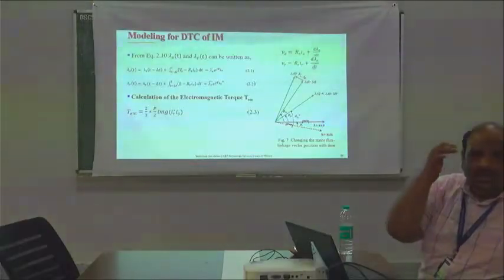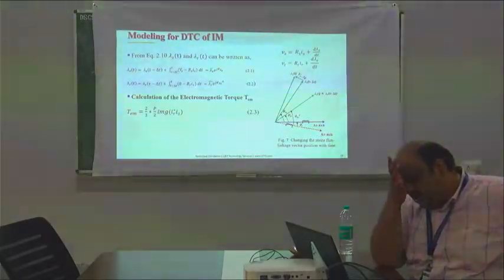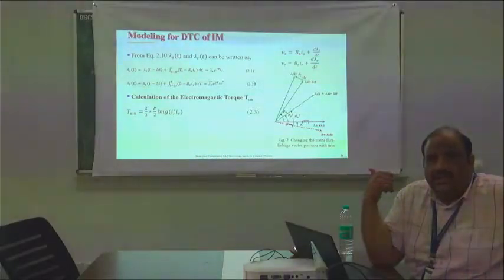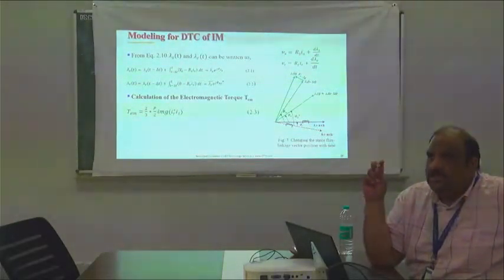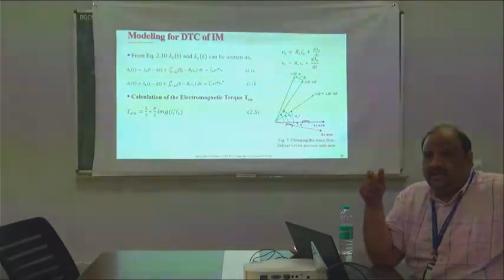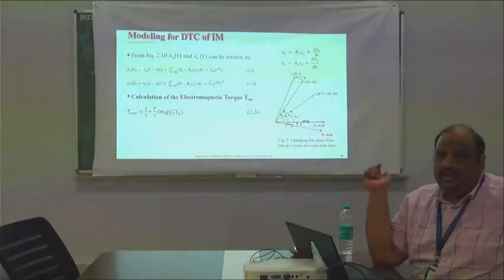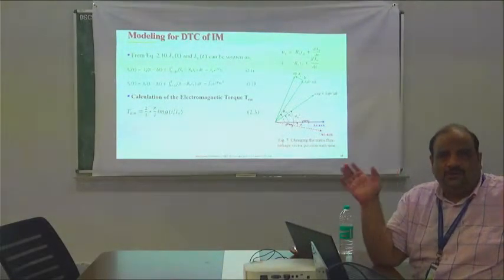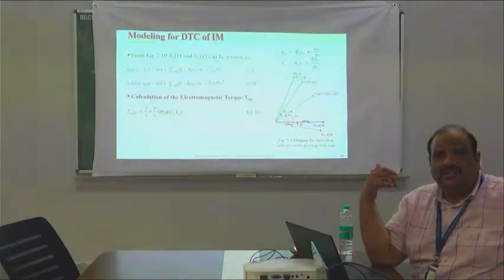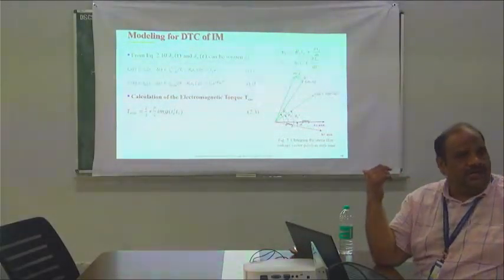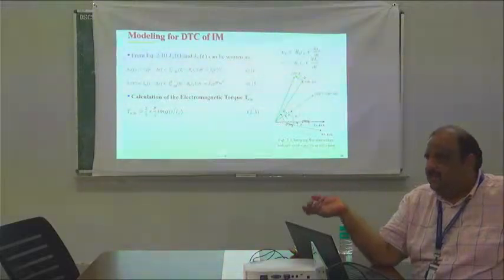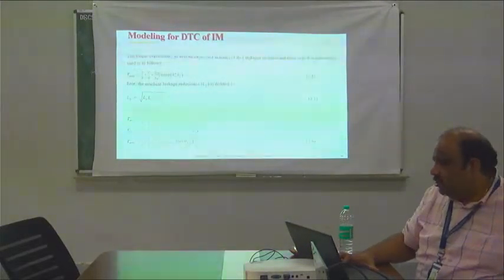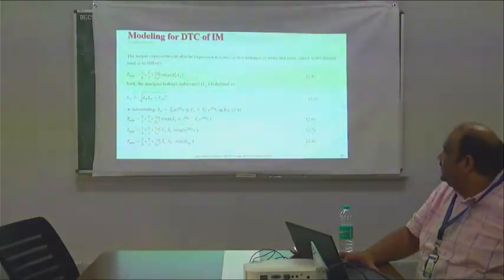Volvo is using direct torque control. Now they have moved to space vector direct torque control, SVDTC. Most OEMs are working with FOC, because we started with FOC. Then DTC, SVDTC: Volvo has SVDTC, and even Mercedes is using SVDTC nowadays. So this is one more algorithm for the vehicle, and again it is simple.